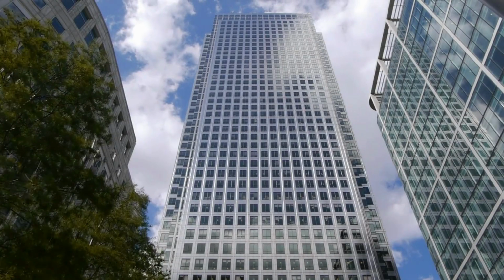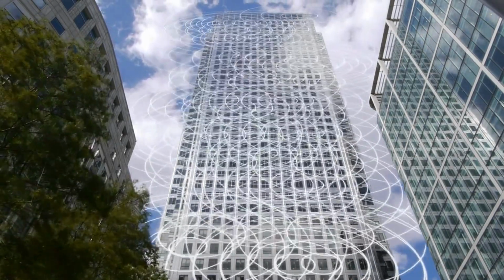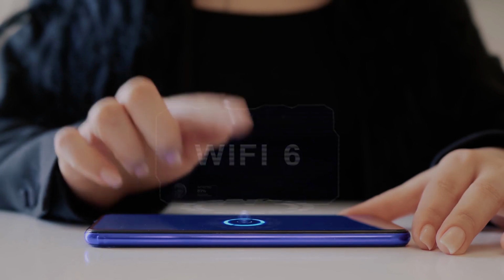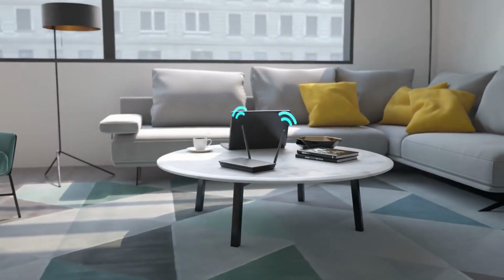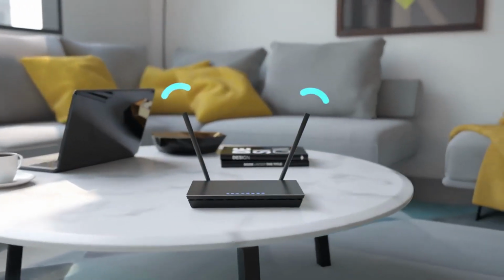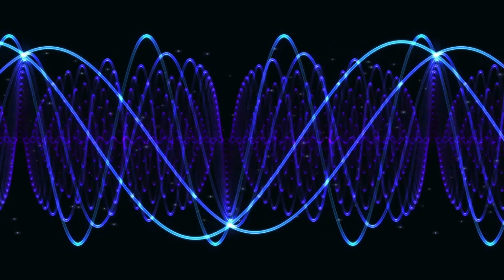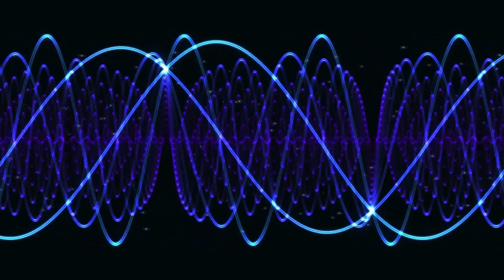These modulated signals are transmitted wirelessly over the 2.4 GHz or 5 GHz band, and increasingly 6 GHz with Wi-Fi 6E. Your Wi-Fi antenna emits these signals, and your router receives them, demodulates them, and reassembles the data. This is the physical layer of Wi-Fi, the electromagnetic wave itself carrying your data through air.